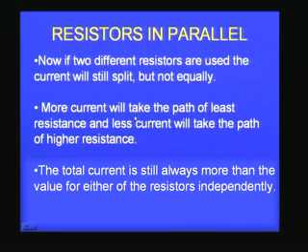So, if instead of using equal resistors for R1 and R2, I use different resistors, R1 different from R2, then you can immediately imagine the two currents that the single current divides into as I connect them in parallel will also be different. In the previous case, the two currents were equal because I used equal resistors. So, different resistors divide current differently, and you know how it will divide. If the resistance is more, the current will be less. They have inverse proportion. If the resistance is less, the current will be more.